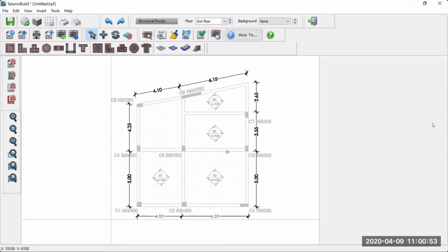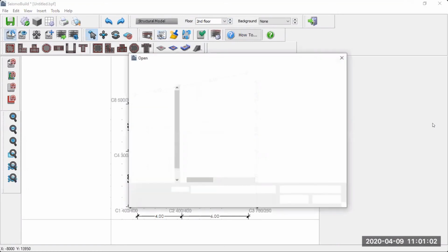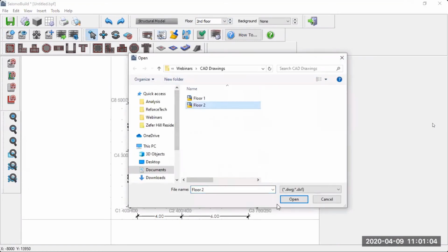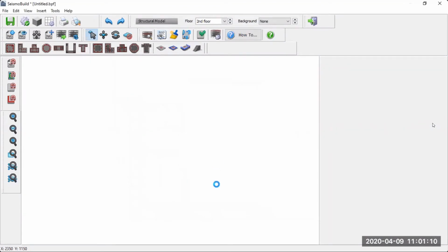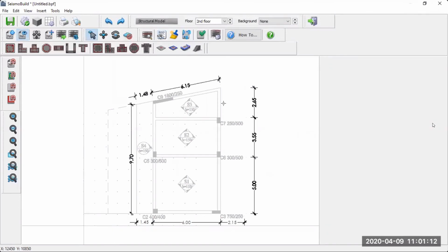So for the second floor here, we want to insert a new drawing, because this drawing is based on our first floor drawings. So we go back to this function again, Import DWG. We select the second floor drawing and insert, and the same function will ask you for the original point, 0, 0. Straight away, this is the second floor DWG drawing.